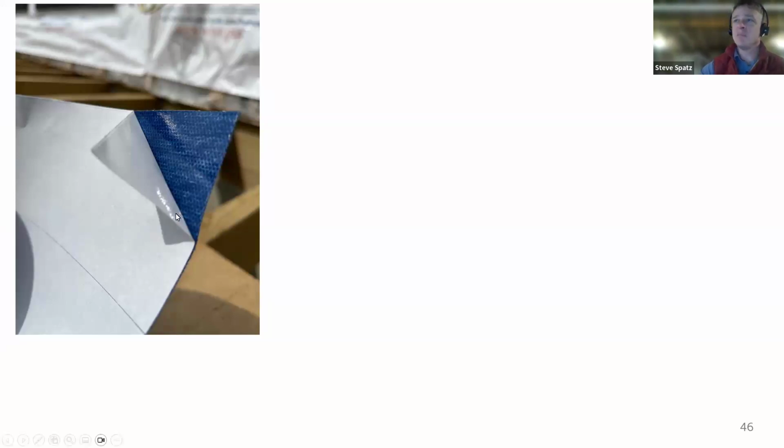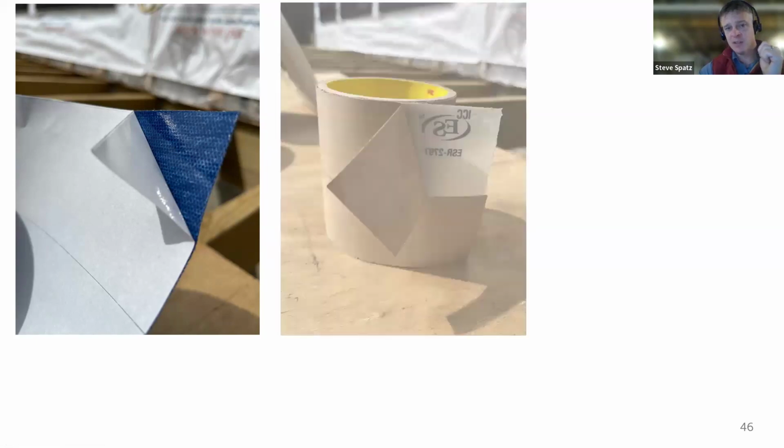So, this is a type of vapor permeable, pressure sensitive acrylic tape that's airtight, but it does allow for moisture vapor to move through it. And the concept being that the substrate that this tape is going to go onto would probably be CDX, and the permeability rating of this tape is similar to what the CDX would be. So, meaning like if you sheathe your building with CDX because you want to have high vapor permeability for the sheathing layer and good drying potential to the outside, the last thing you'd want to use is a type of tape that doesn't have any drying potential to the outside because it's plastic essentially.